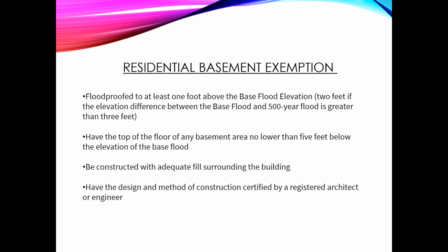But basically, this exemption is allowed for communities and areas that have shallow and low velocity flooding, adequate warning times, and then the basement, as with the definition of floodproofing, has to be impermeable to the passage of water and built to withstand the hydrostatic and dynamic pressures that include buoyancy to the floodproof design level. And so they're supposed to be designed for minimum damage. And again, we have had cases in Kansas where the water flooded a basement that was either under construction or the floodproofing had failed.